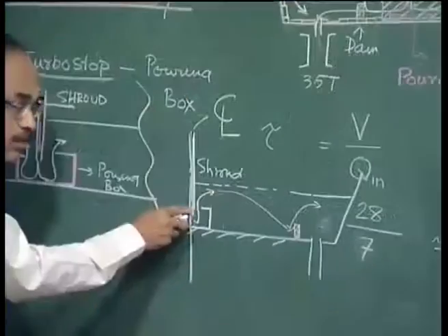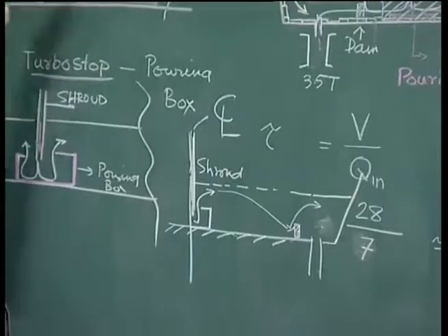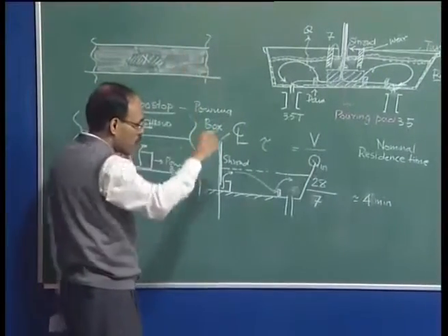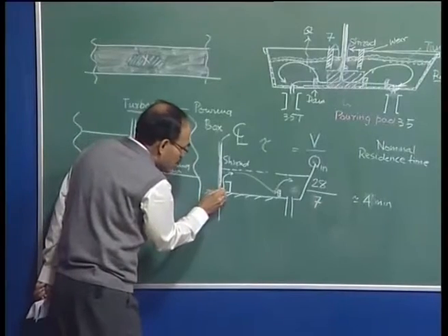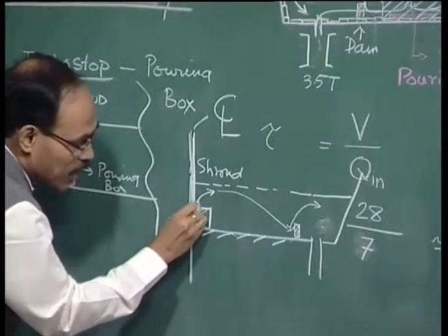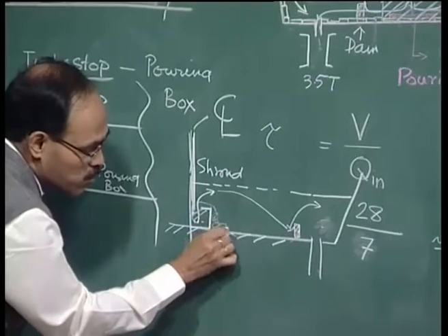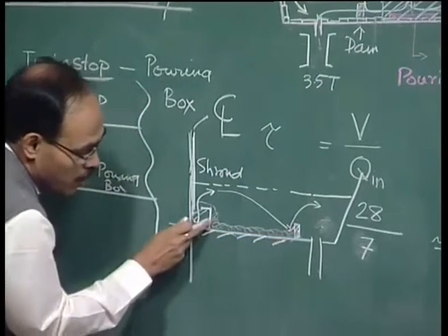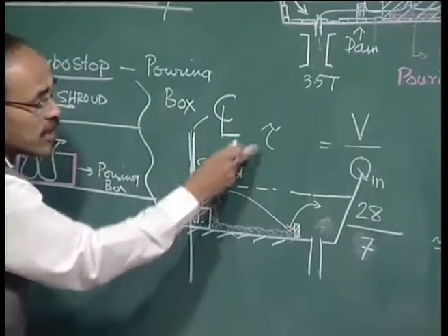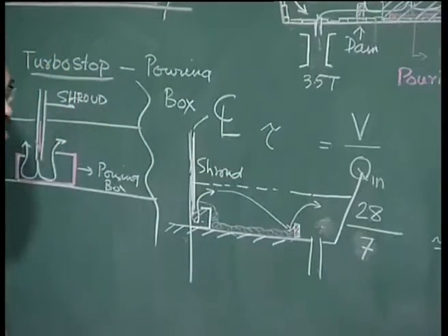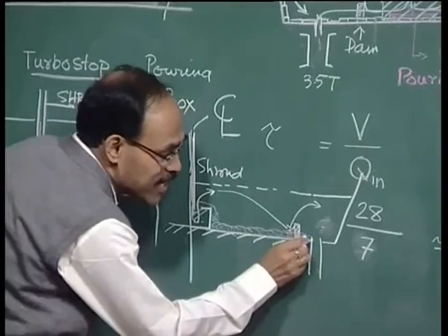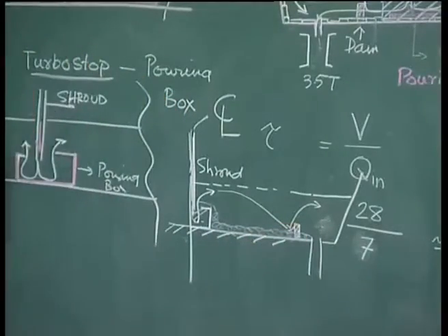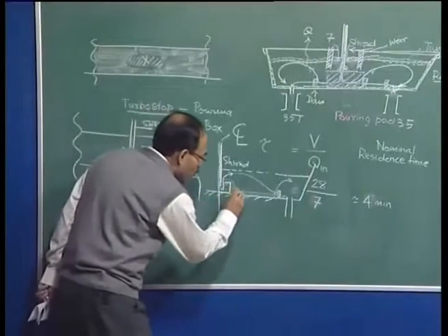So, it is relatively cold, and then the material in the core of the ladle will flow out, and that metal is much hotter. So, as this material fills up this cavity and then flows, the first metal trickles and gradually flows here. The first metal is going to be subjected to a very high level of radiation losses. So, by the time it reaches here, that material can freeze and clog this nozzle. So, we would like some material to pile up here.